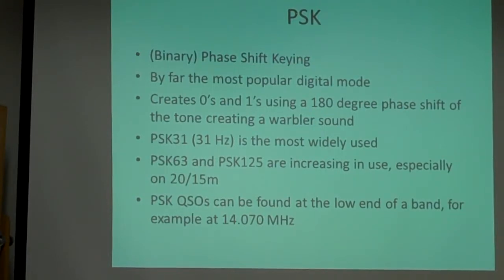The binary phase shift keying, which is essentially just a 0-degree reference and 180-degree reference shift between the 0 and the 1. And then the quadrature phase shift keying, which gets into a little bit more complexity, but has much better characteristics and provides error correction, which regular PSK does not.